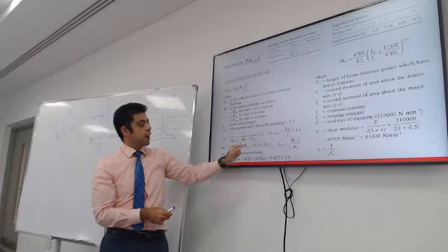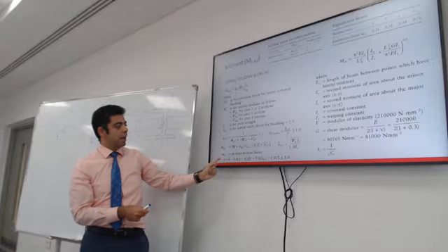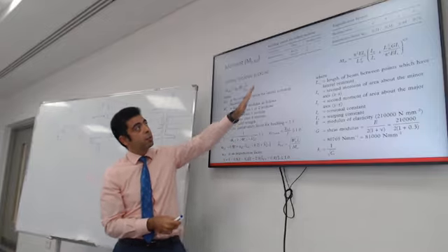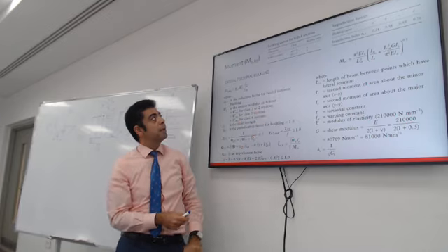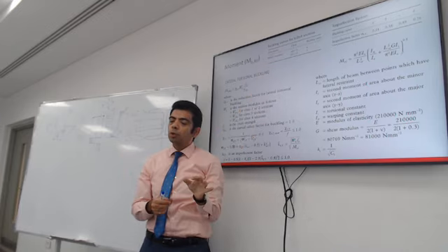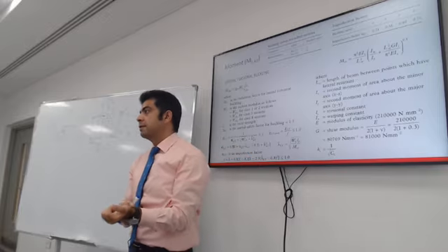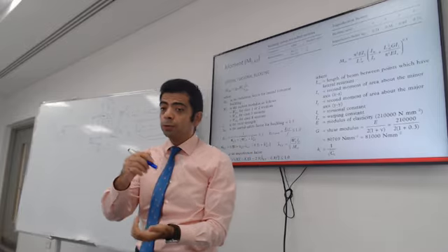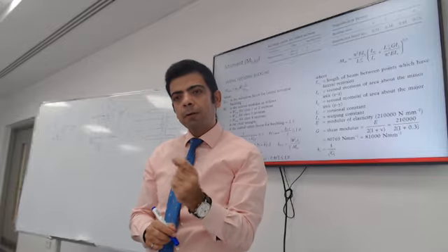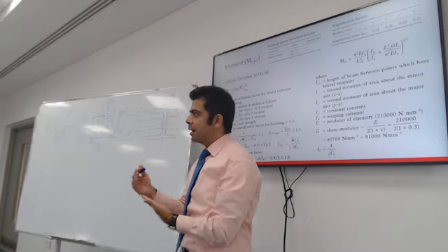So the reduction factor depends on lambda and on the imperfection factor that we can get from the tables over there. And depending on the shape of the cross section, the code will suggest which buckling curve we use. So it's very important that you go through the design process and figure out what you're set for yourself. What are you going to do when it's time for you to design?